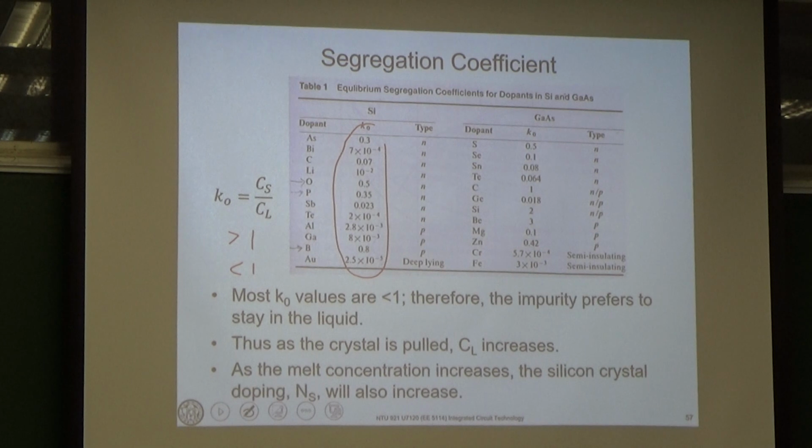Let me say it again in Chinese: when you pull this, because your dopants prefer to stay in the liquid, they move to the liquid, but once it solidifies or turns back to solid, that solid will contain a larger concentration of dopant or impurities.